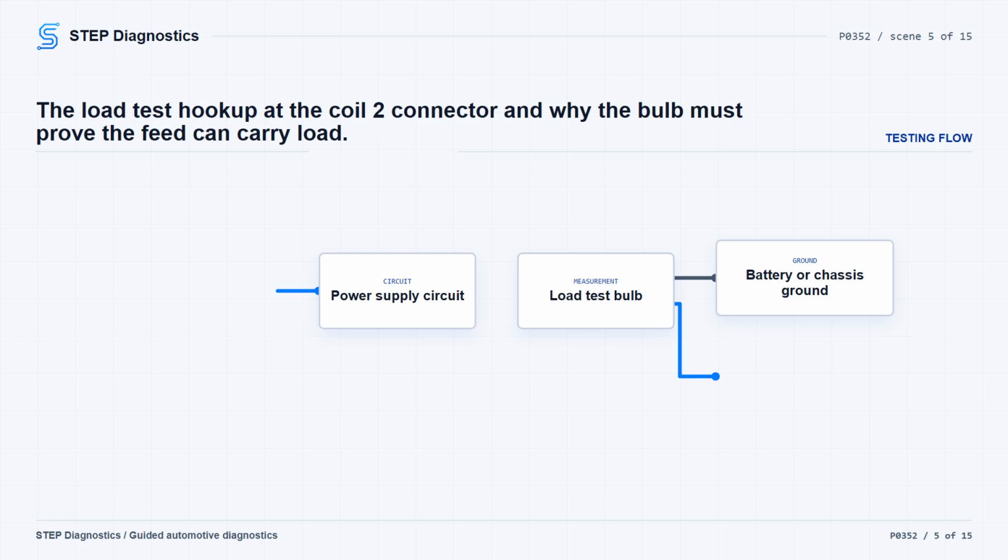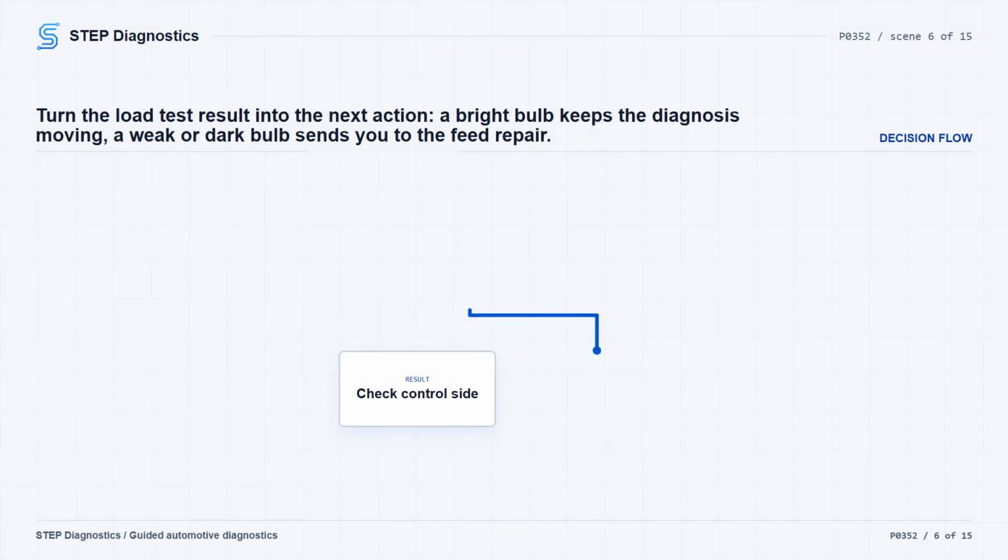Make sure that circuit is actually being powered on. If it is an ignition feed, the ignition needs to be on. If it is relay output, verify the relay is energized and on. The load test bulb should be illuminated and bright, and you should compare that brightness to a direct battery connection. To verify the circuit with more certainty, perform a voltage drop test across the 3156 bulb in the load tool.